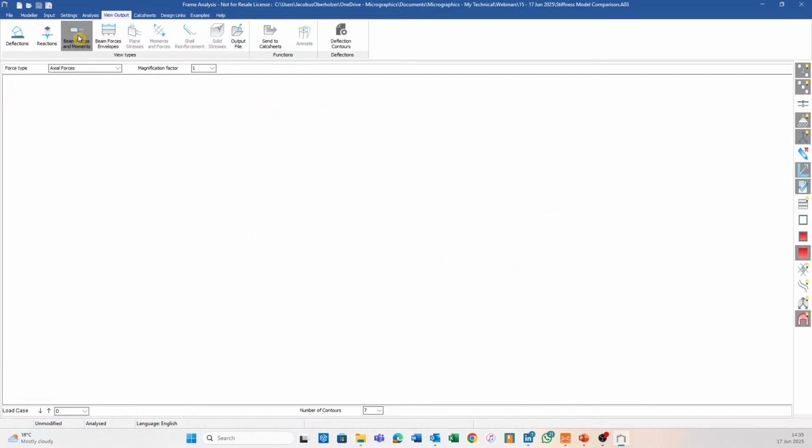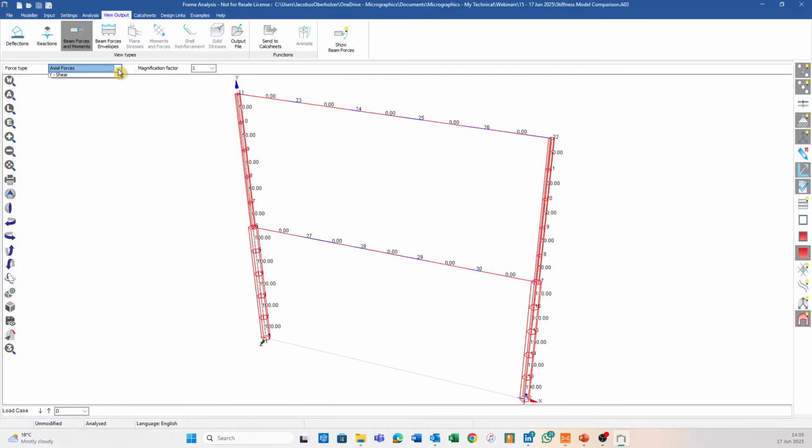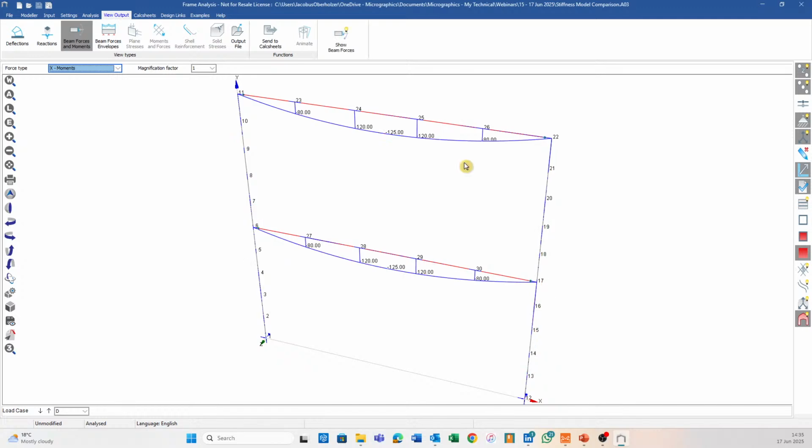And then we want to look at our maximum moment. We know on the edges it'll be 0, but in the middle we'll have quite a large moment of 125 kilonewton meter, whereas the moment for C1 was 102.37. Okay, maximum bending moment in the middle of the beam. All right, so that's for pinned.